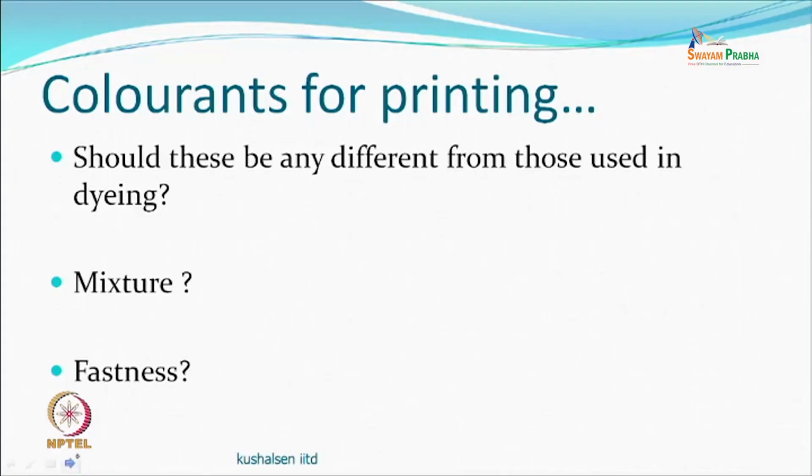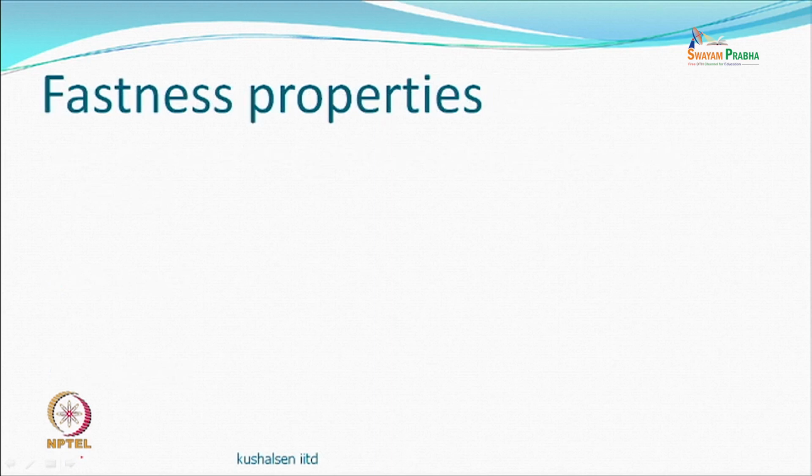And also the difficult part, as we have said already, is that the fastness of each of the dyes in the mixture that you are using should be similar. It will be very difficult to be exactly the same, because the molecule is different. So, theoretically you can expect that every different molecule will have a different property. But if it is in the range, we always talk about some range, acceptable limits, then it will work. So, you will have to depend a lot on the data sheet of the manufacturer and then select the mixtures, and not arbitrarily because this particular one gives such a beautiful shade, let me use it. Later results will not be so nice.